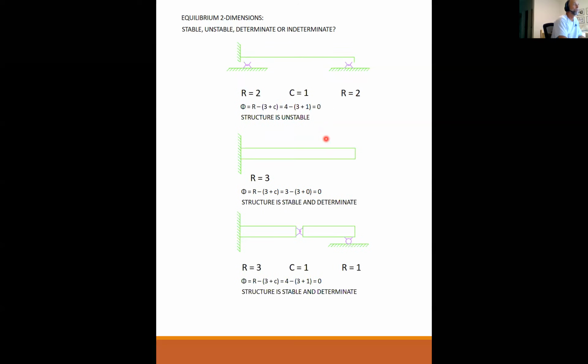And in fact, not to make anybody even more depressed or confused, but I plugged this one directly into my frame program. It's like RISA or RAM or ETABS. The one I use is called Multiframe. I plugged this into Multiframe and it solved it. It's unstable, but it solved it really weird. In other words, the software didn't even pick up that it wasn't stable.